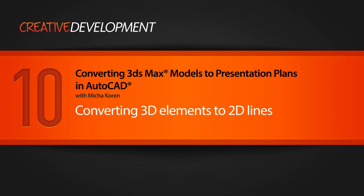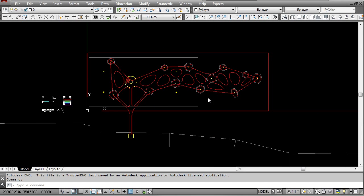In this lesson, we will learn how to use the flatten versus the flatshot command in AutoCAD. Now, the flatten command is something that we covered in lesson number 6, and it is generally quite useful when you have quite a simple spline that is slightly deformed in one direction, and you just want to get it all to line up and be planar to better work into your sections.